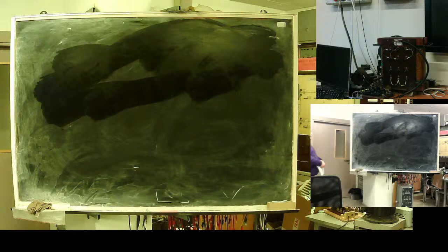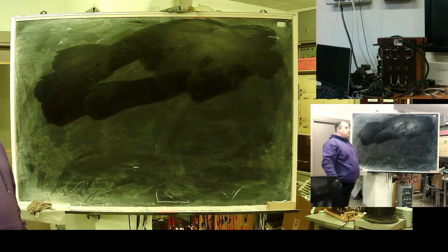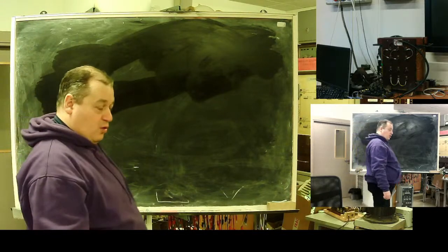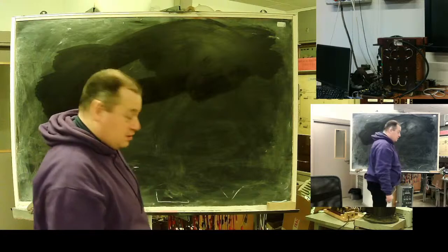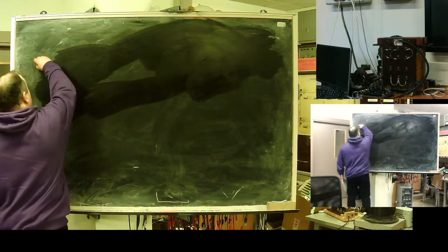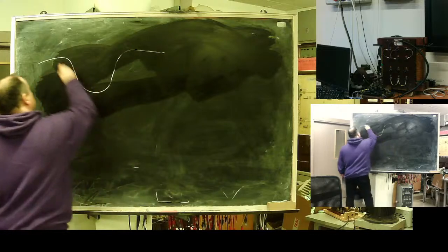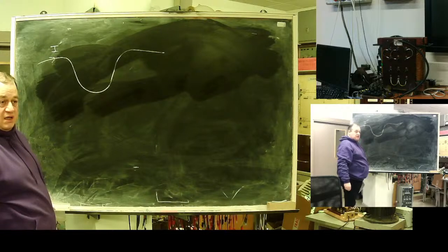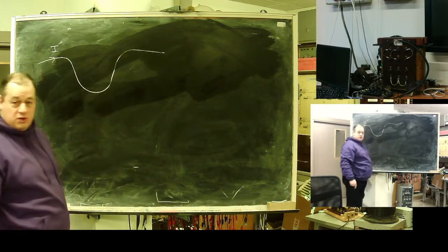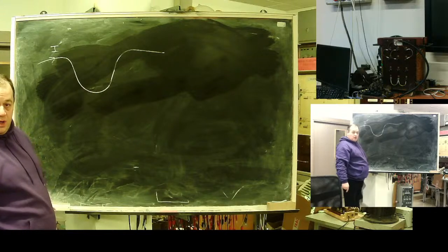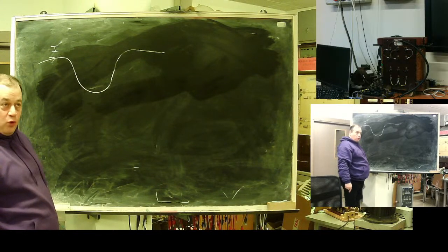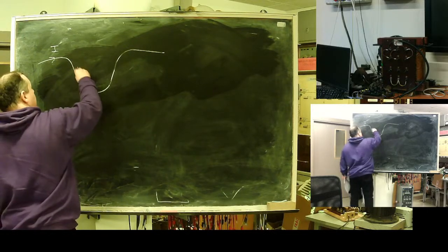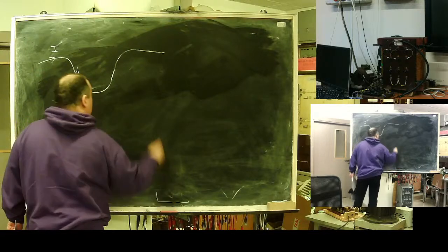What's interesting in nature, in real measurements? First thing, the guys tried to build a line and measure real values. If your line makes a loop, it can be expected that the ground current will flow through the shortest path. No. In reality, the ground current follows the line. So if the line makes a loop, the ground current follows.